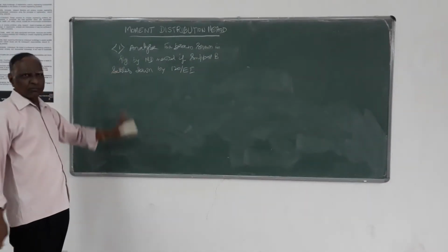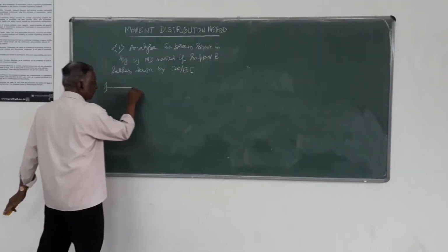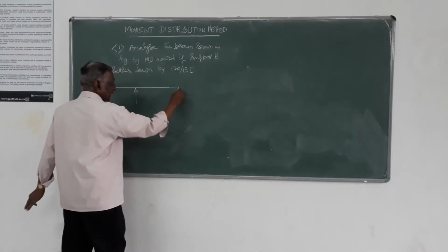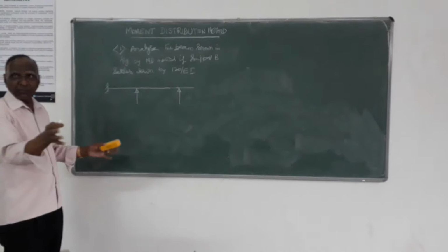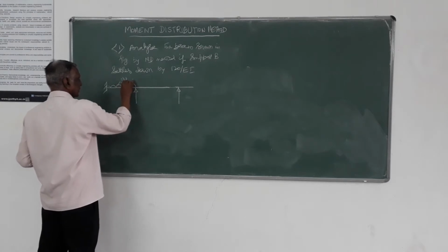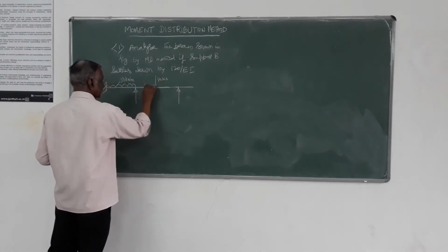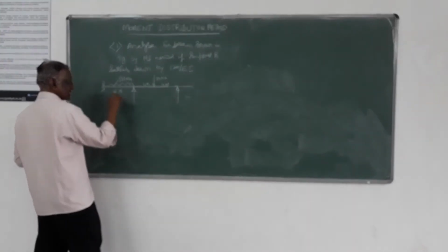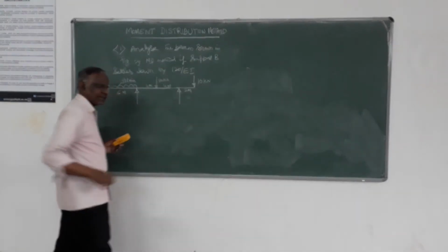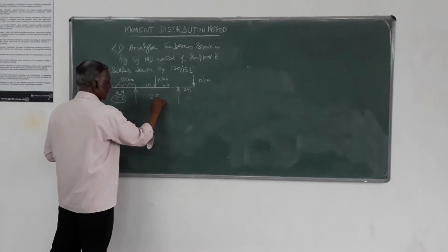Now we will take up a beam problem, analysis of beams. The same example we worked in the slope deflection method, we will work in the moment distribution method also. The three problems you did, analysis only for the member loads, that is this 50 kilonewton per meter, 80 kilonewtons on this member, which is 4 meters, here it is 6 meters, along with an overhang load of 10 kilonewtons at 2 meters, and the flexural rigidity being EI, here it is 2 EI.